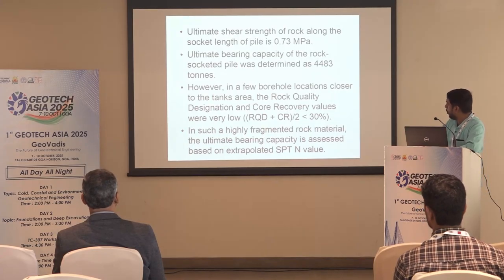And however, in few boreholes located closer to the tank area, the rock quality designation and the core recovery values are very low. In fact, RQD plus core recovery by 2 will come less than 30%.